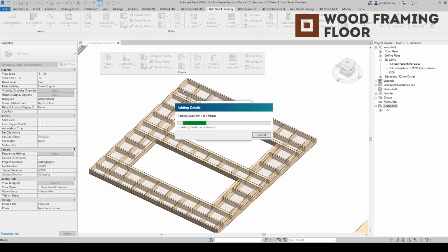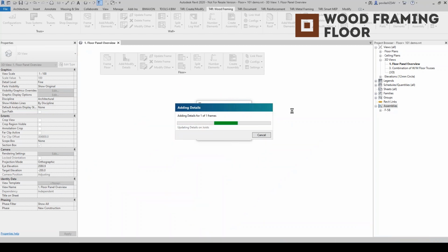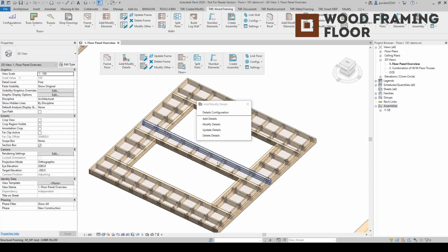All the details are customizable, same as all of the configurations that the floor would need to have defined. So you define configurations prior to framing, and then you just click on framing. Later on, you're going to split parts. At the end, you're going to produce shop drawings, and if you want, you can export to CNC machines as well. The detail is in place.